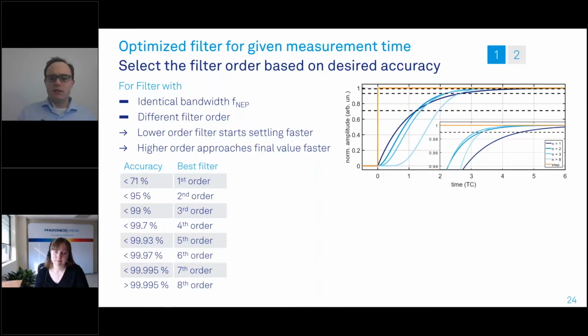You adjust the filter order a little bit, then you optimize the filter bandwidth, because every signal is slightly different, and you need to look in detail at how to do it. But what I can say, what is very typical, a very good starting point for typical step scan measurements, for example, is always, I would say, a second or third order filter.